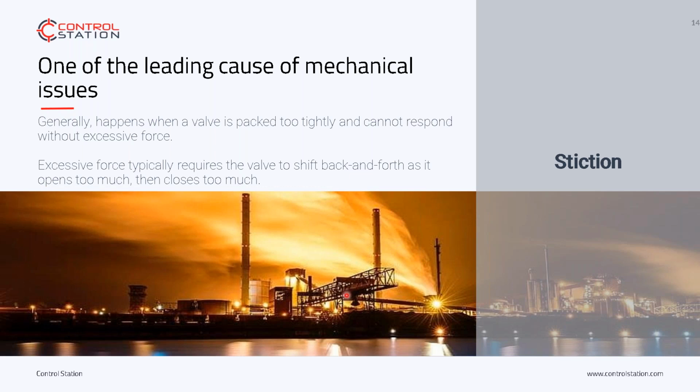So let's have a look at a couple of those 3 components. We'll do stiction first. What is stiction? Well, it's one of those modern makey-uppy words. Stickiness and friction have been combined together. The valve has got stuck due to friction. Now, the friction has been caused by the packing, or the seal on that valve, has dried out, has overheated, has been overworked, and is causing the friction between the packing and the valve stem to exceed the break free load that the pneumatics are putting on the actuator.